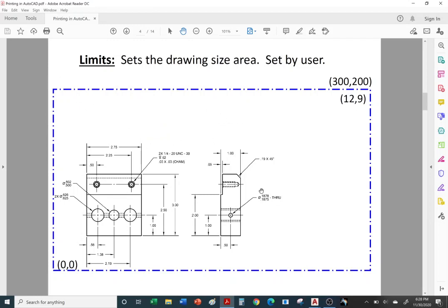What you do want to include inside is things that you want to print at the very end. Once you're done with your drawing, you want everything that you want to print inside your limits. Sometimes you'll have an extra view or a backup view, which you want to set outside the limits. If you're not sure if you want to delete a view or update it, make a copy and place it outside your limits. Or sometimes you can put notes for yourself. At the end of the day, I might put a note to myself: Hey, don't forget to dimension the whole pattern in the top view. I can put a note to myself outside the drawing limits, or maybe put a note for somebody else that may take over your drawing. Leave some notes outside the drawing limits using the text command.